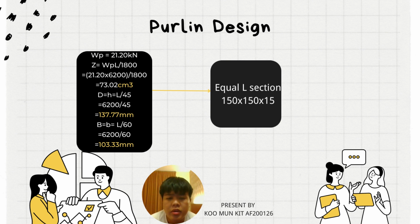The WP in the purlin design is 21.2 kN. Then we use Z equals WPL over 100, and the value calculated is 73.02 centimeter cubed. Then D equals L over 45. We use 6,200 divided by 45, and we get 137.77 millimeters.